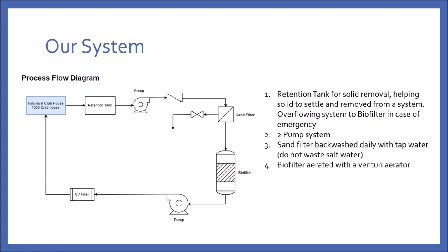Note that we are utilizing a 2-pump system instead of a single pump. And the sand filters are being backwashed daily with tap water in order not to waste any salt water. The biofiltration is being agitated with the pump, and it also, at the end, performs what we call aeration as well as circulation.